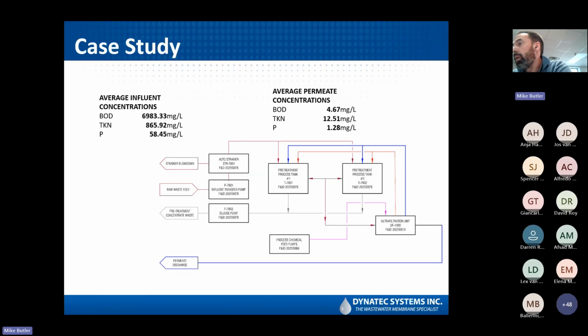And then when tank number 1 reaches its maximum concentration, process tank number 2 would be used to feed the ultrafiltration system, and it would switch back and forth on a daily basis like that, allowing you to concentrate the waste as far as possible while treating it quickly. We don't want to run the same tank for several days in a row, because some of those things will solubilize and will not be removed by the ultrafilter if we let it sit longer.